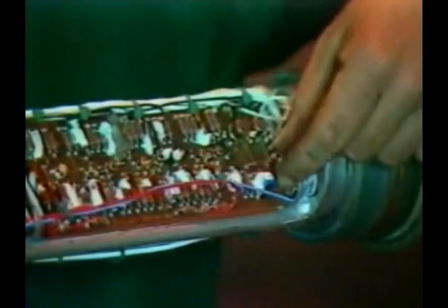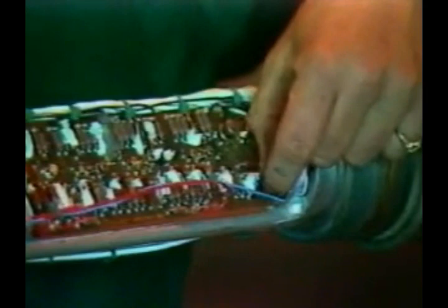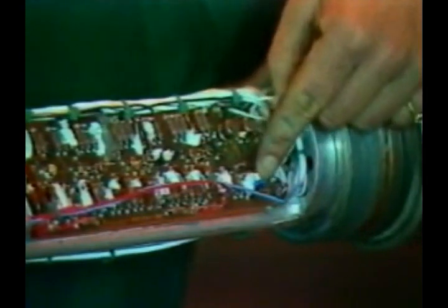Still other devices use built-in calibration tests, like the internal resistors in this resistivity tool. All before-survey calibration check data are added to the permanent records of each individual logging device and are included in the final printout of the logging survey.